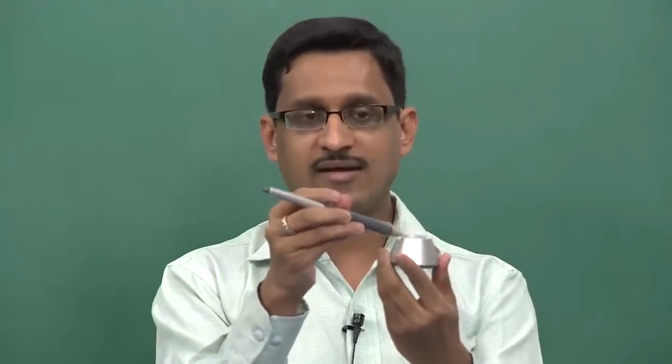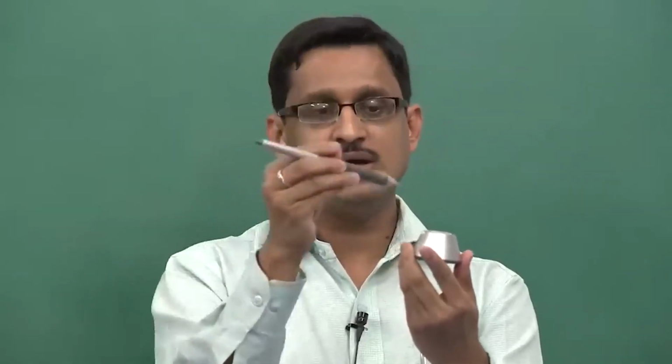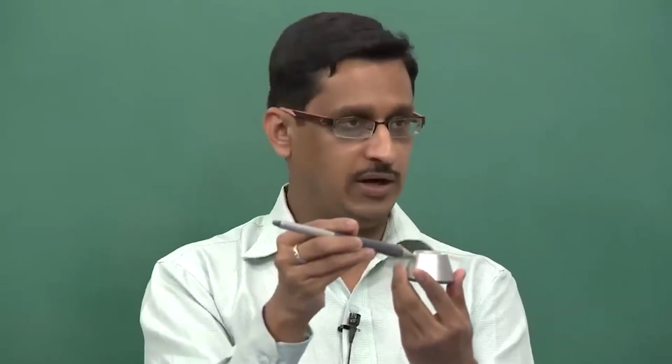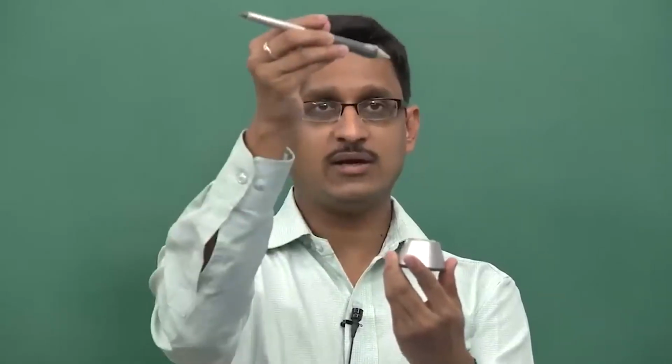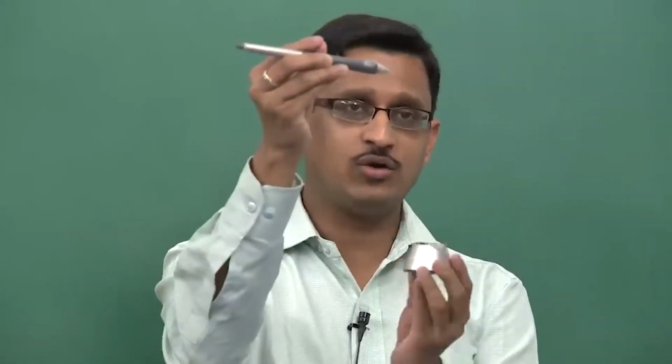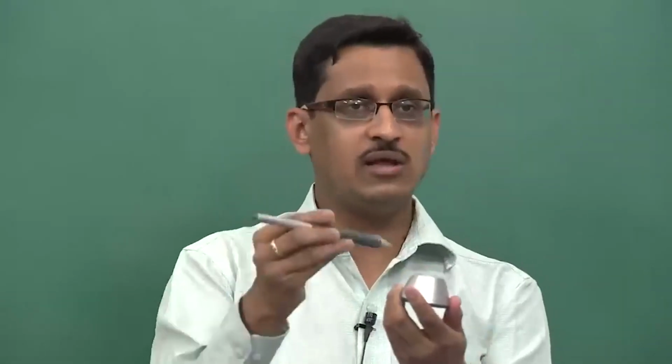Now, you can translate it parallelly. Mathematically, a vector that I am showing here and a vector here are both equivalent. However, physically these two are not at all equivalent. This vector is not at all acting on this object, or you could translate it down in the same plane. Again, the two vectors are mathematically equivalent, but they are not physically equivalent.